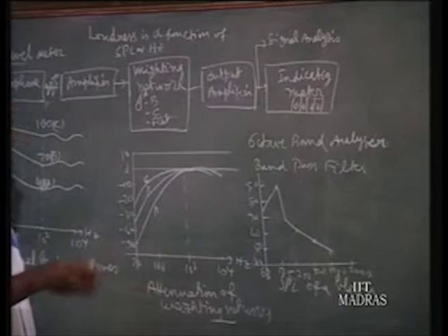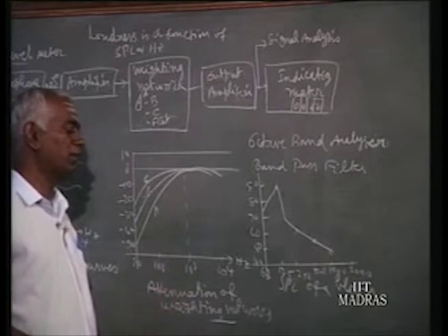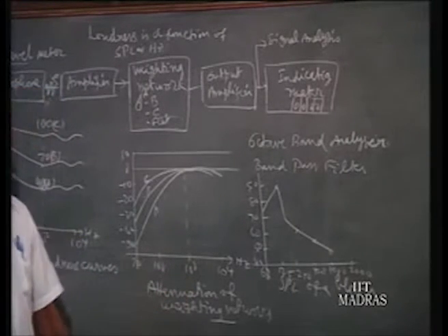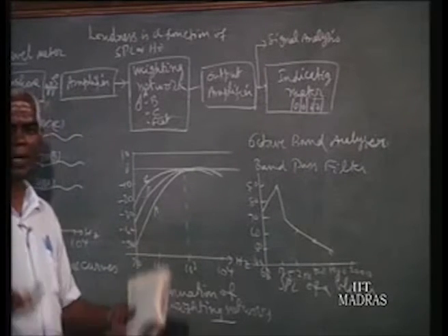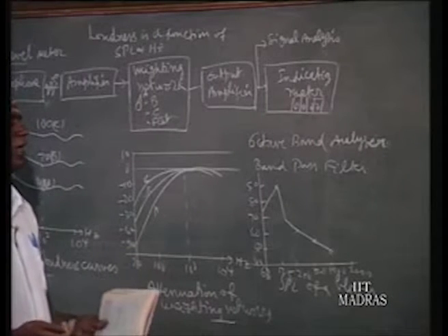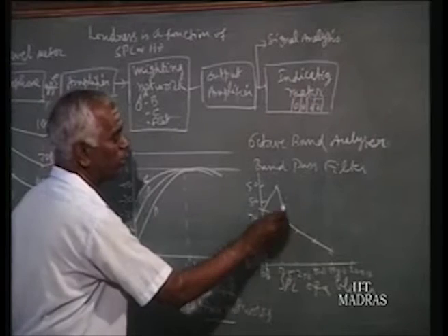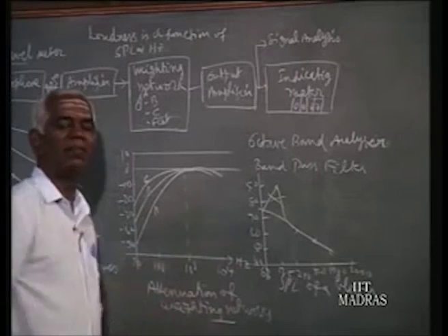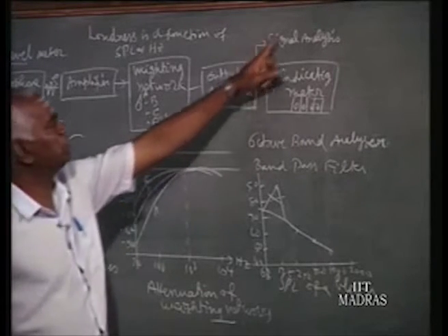Then we find one of the two gear machines, one of the two gears, and we change it. If they are metallic, we can change one to, say, a plastic gear. A gear machine with a plastic gear and a metallic gear will make very little noise. Then after making that change, measure again, and you will find this will go away. Like that we effect improvement in reducing noise in many equipment. So for that purpose we can analyze this signal also.